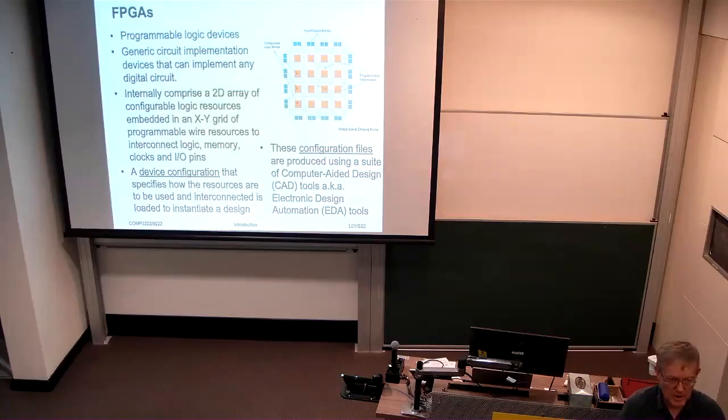To program that tool, though, we use the language VHDL. You could use Verilog. It has to be one of those IEEE standard languages. And that allows your design that's written in VHDL to be taken from one device and put onto another by just using the tool flow that targets that vendor's device, as it were. So you're going to be learning about VHDL as the input language to this tool called Vivado. Is that what you're after?